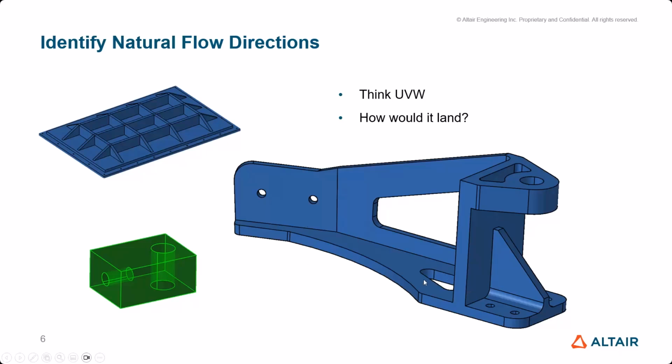There's obviously a length direction, but then it goes around a corner, and there's almost two pieces here. This is the main part that I'm going to demo today. In this case, if you just split it at this face here, then you have an angle there and a little bit of a bathtub fitting here, and the flow directions become more clear. You also have to encounter things like, this is a very simple model at first glance, but it's actually a pretty complicated problem when it comes to hex meshing, because you have perpendicular features that you have to reconcile.